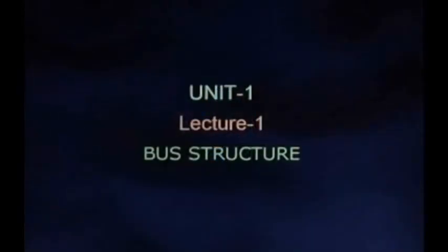To ensure that no output of one logic device is connected to the output of another logic device, although each one of them is connected to the inputs of other devices, and in the process they get connected together, we have to adopt a new technique. This new technique is what we call a bus structure. Before we go into the details of the bus structure, we will first explain briefly the various components that are present in the digital computer.